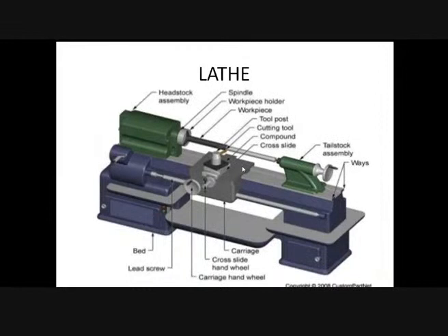The second topic for lathe bed is material. What material are we using for manufacturing of lathe bed? The bed of the machine tool is made of gray cast iron because the presence of cementite in granular form in gray cast iron gives high damping qualities in addition to high rigidity. You should not only have high rigidity, you should also have high damping quality. So in order to have high rigidity plus high damping quality, we choose gray cast iron as the material.